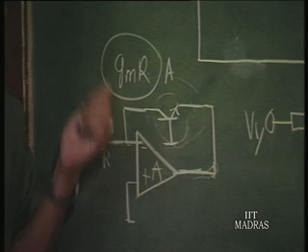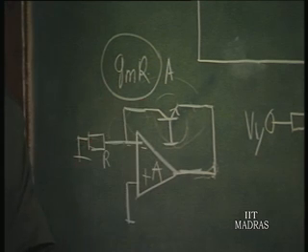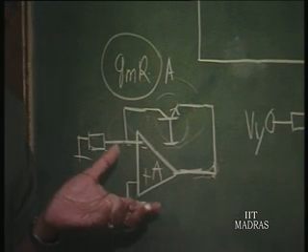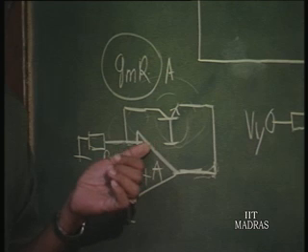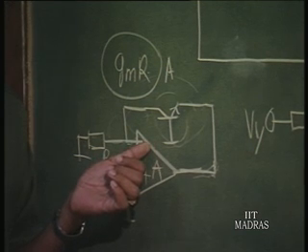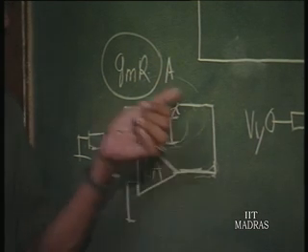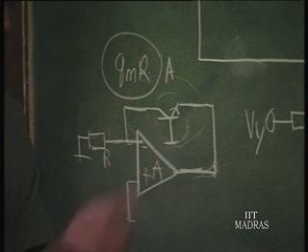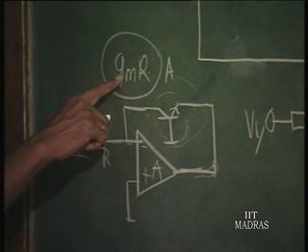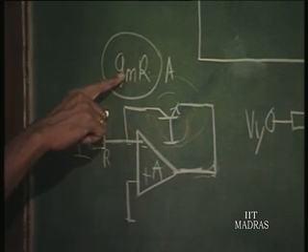So, this will go into oscillation. How to prevent this, or how to use a compensated op amp here and not cause any oscillation in this circuit? That can be done by reducing the gain here. So, that means Gm has to be reduced.